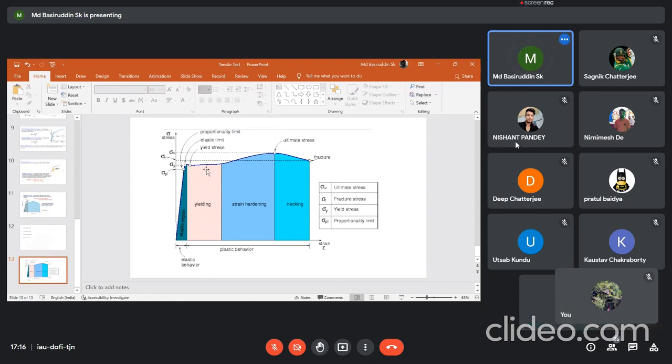The dislocation defects are generated, and the carbon and nitrogen sit in those defect areas. It will resist the propagation of the dislocations from one atomic layer to another, requiring a little increase in load.